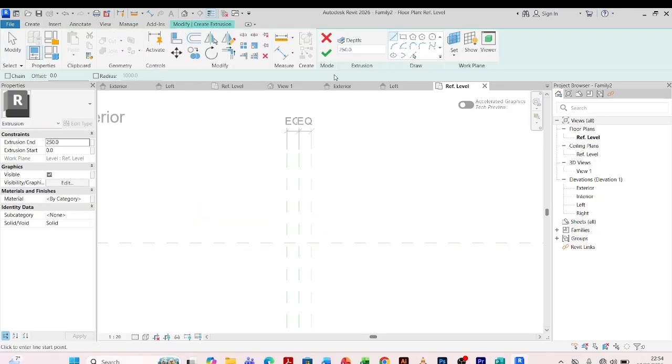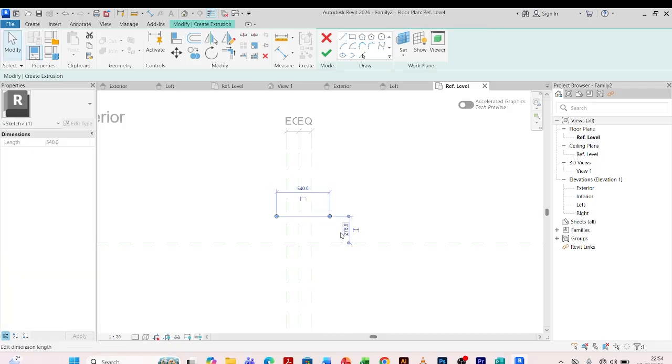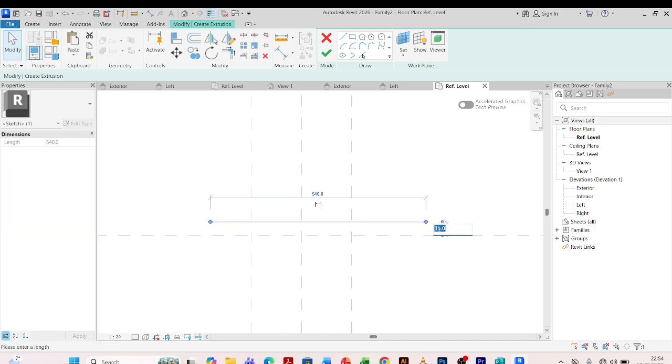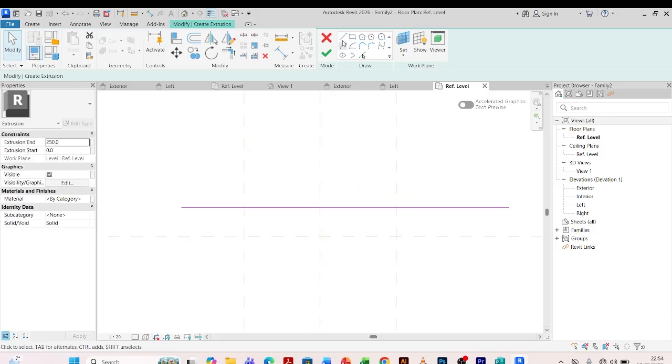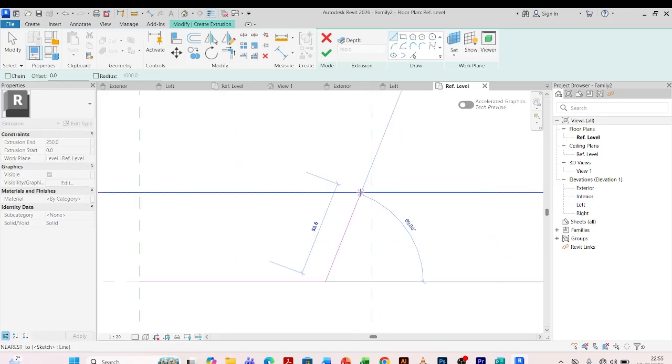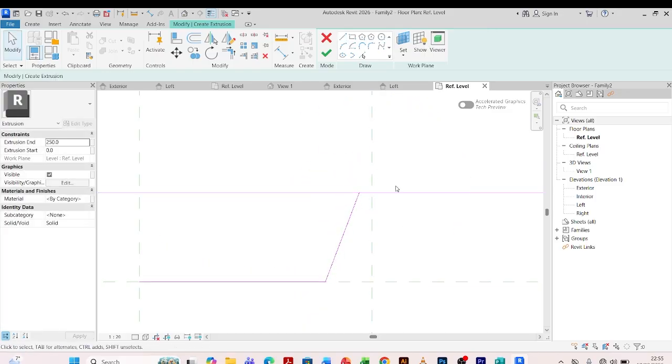I'm going to create an extrusion. First get the height. The height still we can go with 50 or even less. We can go with maybe 35. Let me give it 50 so that we are kind of uniform. So I'll have this line drawn maybe up to 100. Then I curve this at some angle. You can go with 70 and right there. I'll delete off this, something like that.